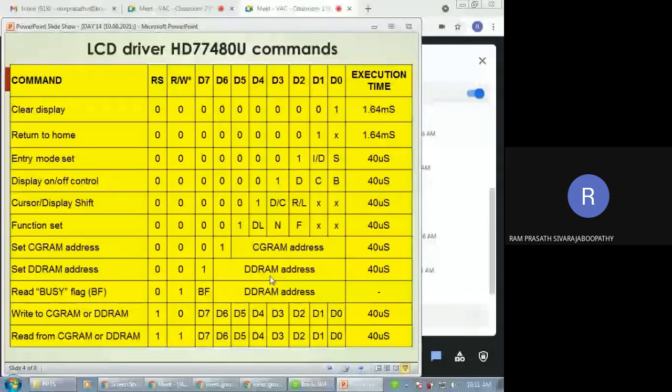So mess[0] means the very first character available in the array, whose ASCII value is written. Similarly, user-defined characters can be accessed with the ASCII values from 0x00 to 0x07. I hope it is clear to everyone.